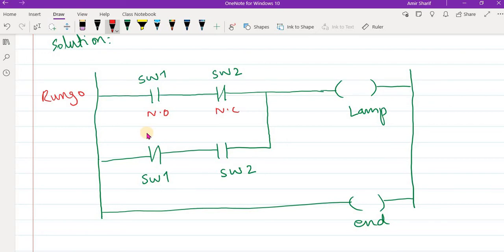But if you close the switch and switch 1 is also closed, this is another condition, then your bulb will start glowing. And if you want to turn off this bulb, you just have to turn off switch 2, and that's how you control your bulb from either your ground floor or your top floor, where your switch 1 is located.